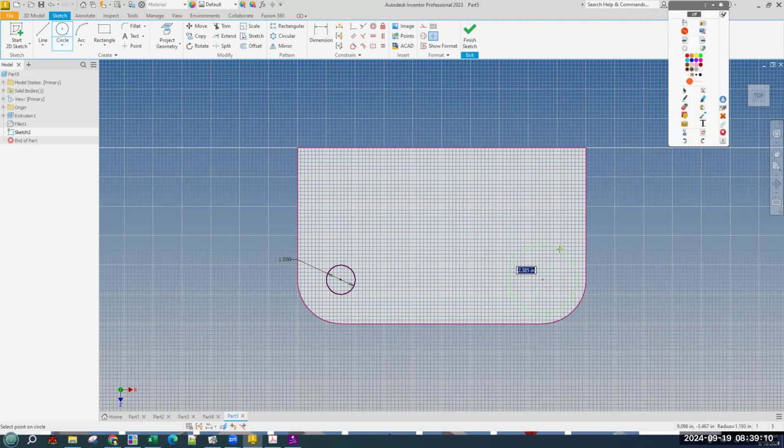If you don't click to set the circle, like you just click to start the circle where you want it, which will be a green snap. Before you click to set it, you can just type 1.5 and hit enter, and it will finish the circle and give it the dimension in one move. Except again, I'm wrong. It's 1. So yeah, it's only useful if you do it correctly.